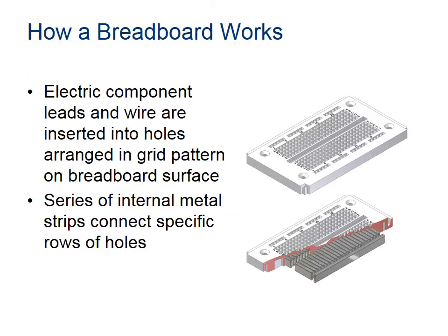So let's take a look at how a breadboard works. If we were to take a breadboard like the one on the top here and peel away or cut away some of the plastic layers, what you see underneath are really some strips. You have a long strip here, which corresponds to the power input or output up here, and then across the rows you see another strip, and they are separated. You need some connections to make those work. Let's explore that on the next slide.